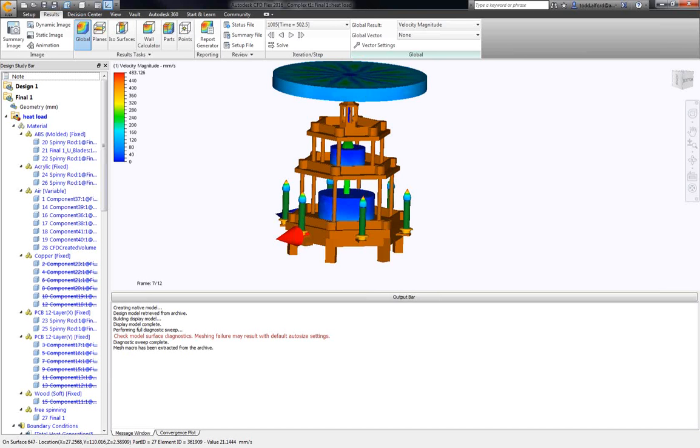How to set time intervals. Thanks for asking a question to burn some time. Time intervals are set within the solver dialog. You can set the intervals for saving intervals, or you can set to save based on the summary file. And you can set up a table as well to drive how often you save those intervals. Just be careful not to save too many. More recently, I try to limit that to about 20 or 30, depending on the size of the model, because you end up getting way too much data within the design study, and sometimes that can really bog down performance. You access it through the solver dialog, and there's a little caret or arrow that expands the solver dialog down so that you see some extra options. So findability isn't super easy unless you know it's right there and you notice that line.